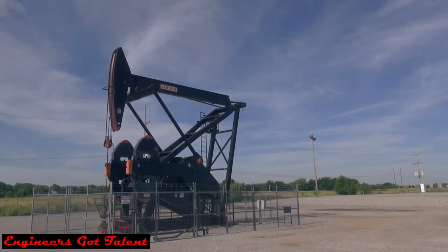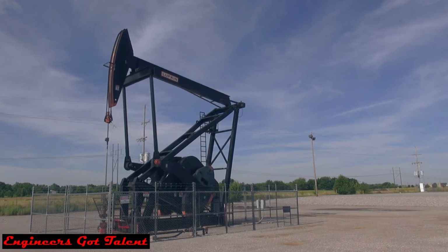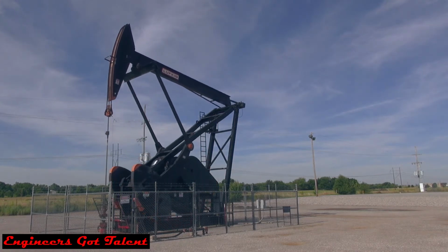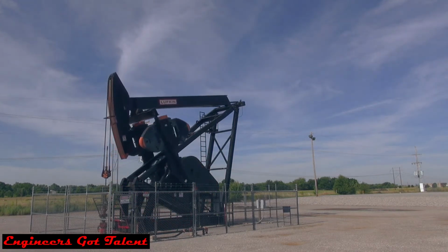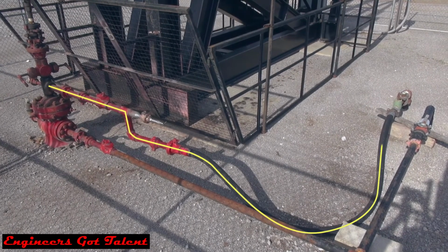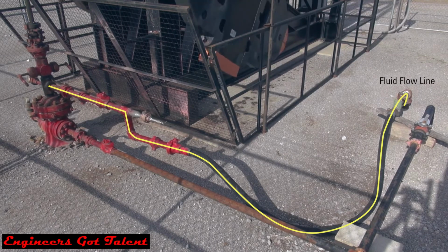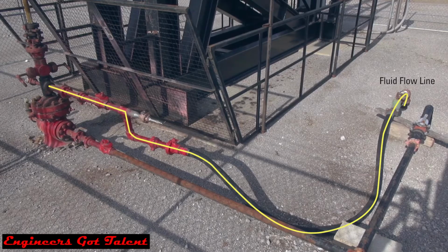This is a wellhead. This is where it all begins. The producer has drilled his well, in this case has had to set a rod pump and a pumping unit in order to get the liquid to the surface. We'll follow the wellhead and go to the flow line to start the separation process of oil, water, and gas,